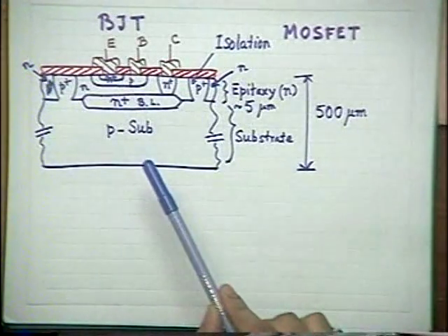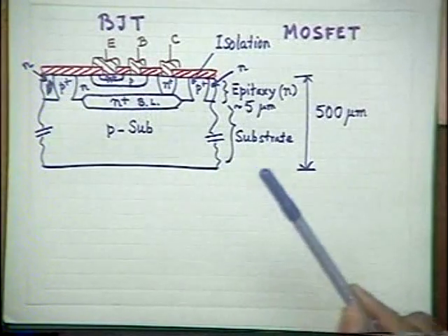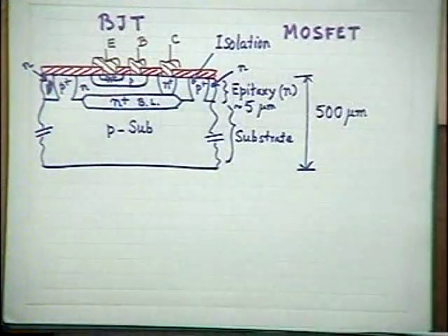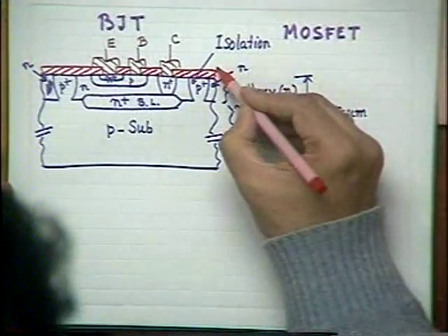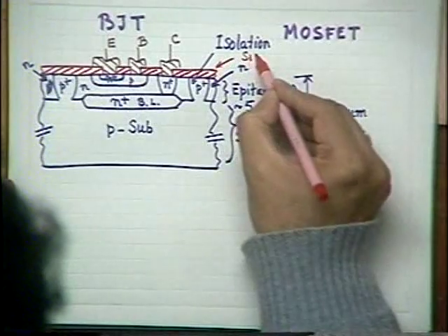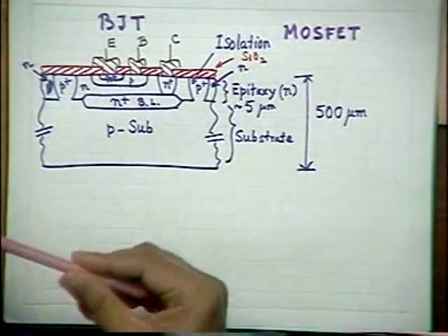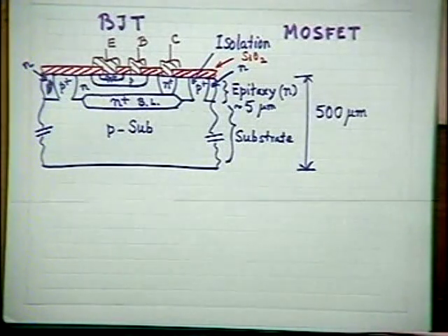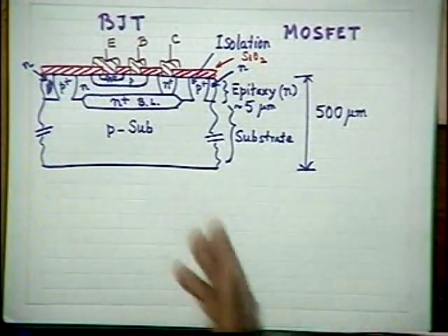And because the material is silicon and not germanium, what is the advantage of silicon over germanium? Silicon is a wider bandgap semiconductor, so its leakage current is very less. Its temperature sensitivity is also quite less compared to germanium. That is why, and technologically silicon is superior, because this oxide which I have shown here, the red region, is nothing but silicon dioxide, which is grown by a thermal technique, simply by oxidation of silicon using oxygen or wet oxygen, oxygen plus water vapor. And this is a very simple process.